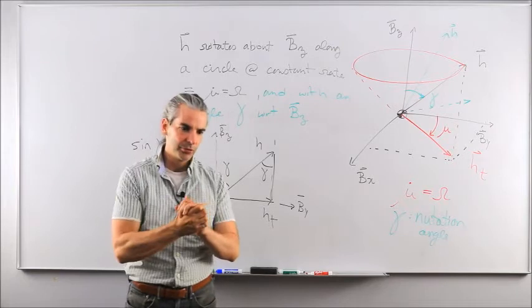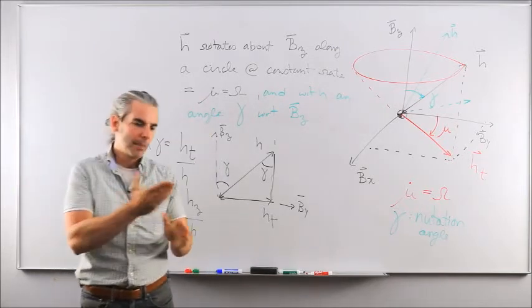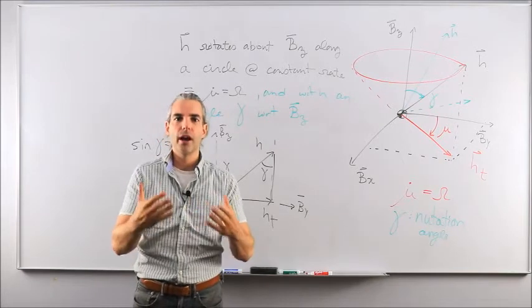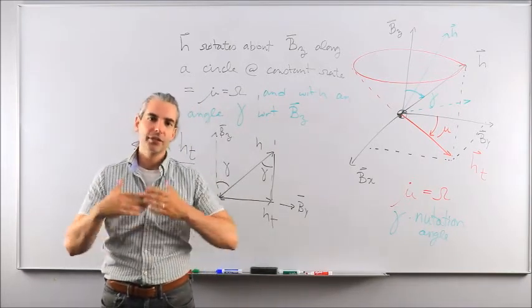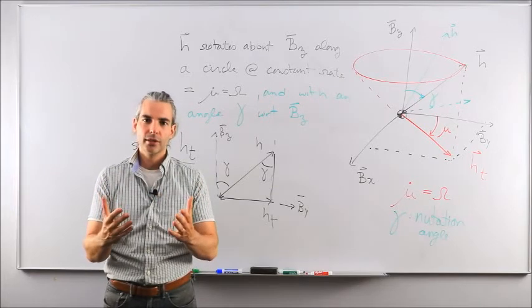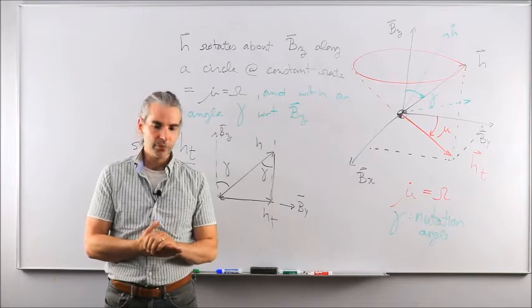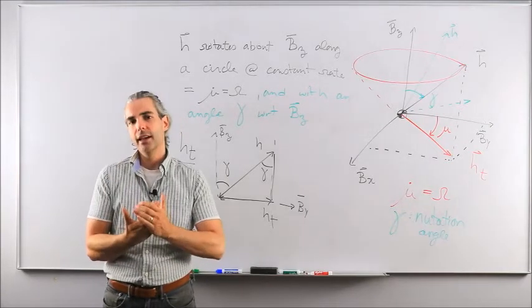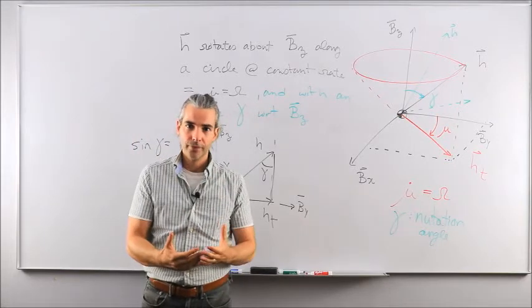Based on the axisymmetric geometry assumption and the torque-free assumption, we went back to our earlier equations derived for a principal axis reference frame and revisited those equations by plugging in those two assumptions. And then we discovered right from the get-go that omega z was equal to a constant and equal to its initial value.